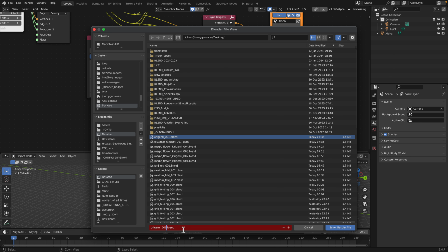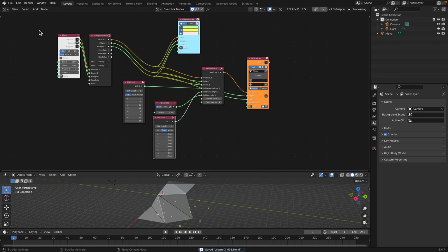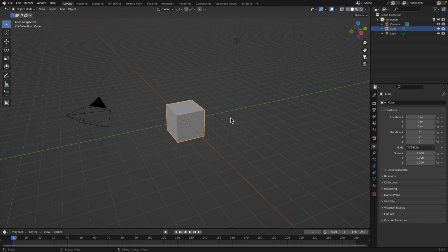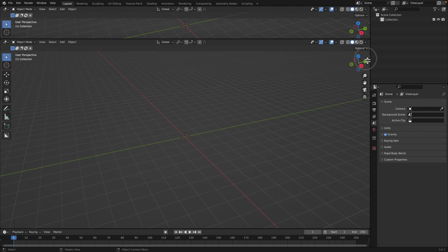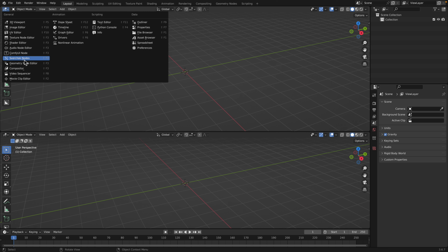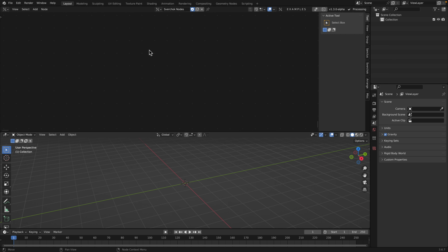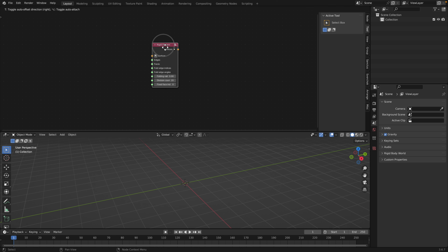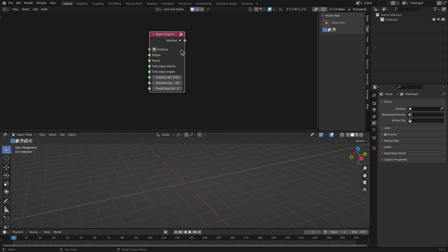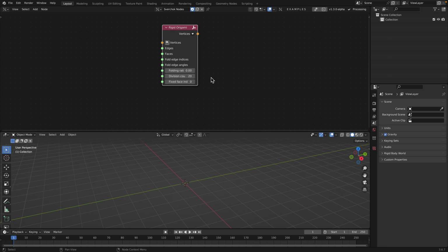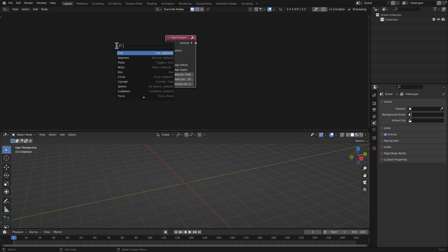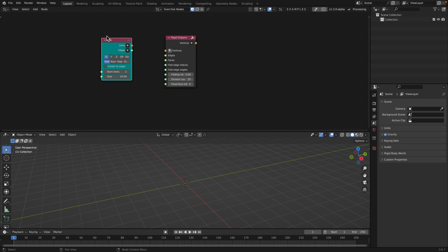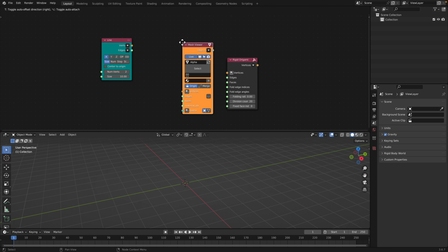Let's try something a little bit more interesting. Start from scratch so I can explain it again more clearly. Delete everything. SVerchok, SVerchok nodes, new, Shift A, create origami, okay, rigid origami nodes. This node used to be a script node light SNL node, like a custom node, but this one is now a real node. It's a lot faster. Let's create a line. Start with a line. Mesh viewer.